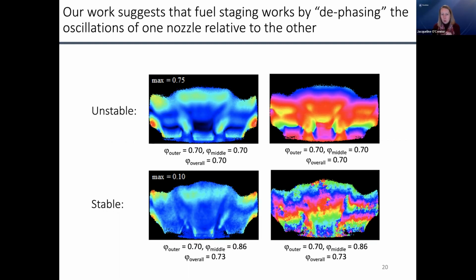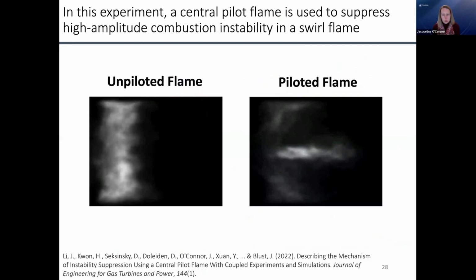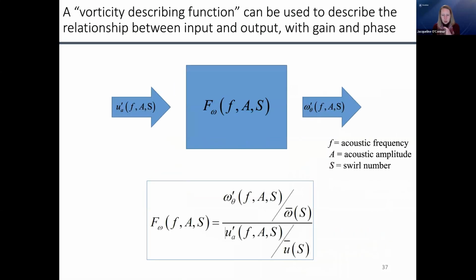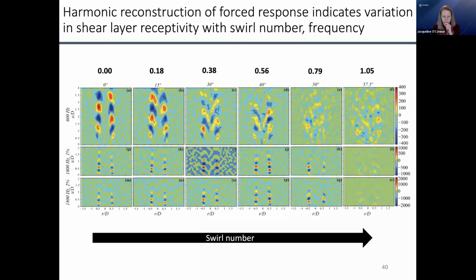But when you have more complex motions, or you have multiple motions, so all the work that we've done on swirling flows, and again, if you look on my lab website, anything with Ashwini Karmakar's name on it, we've been using more advanced techniques because we're looking at how the coherent and the turbulent interact. And so, yes, everything you mentioned is in our toolbox and can be really useful. But my first go-to is always the lowly FFT, because it at least gives you a first cut if you know what your frequencies are.